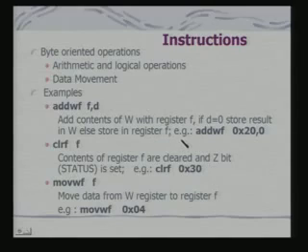So actually when you will be using this, you will be writing it in this form. So this actually represents a memory location in the bank, and this memory is part of the PIC chip itself. It's in the register bank. That location you are specifying, and then you are telling this is 0. That means the result will be stored in W itself. So you add the content of this location with the content of the working register W and store the result back in W.